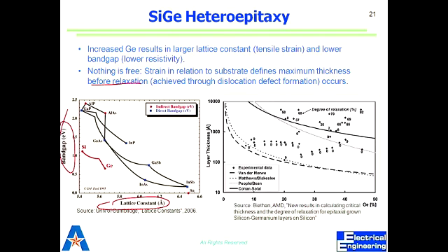Right. So ultimately, it boils down to your band gap energy. So in this case, we can change that band gap energy. And direct and indirect has to do with where those bands lie in the energy diagram. Right. So that's what we call direct or indirect. But the bottom line is that going from one fraction to the other, we change the lattice constant and we change the band gap. Band gap energy change results in a different threshold voltage for us.